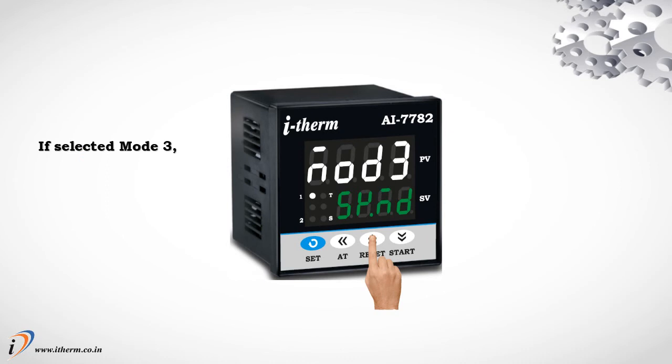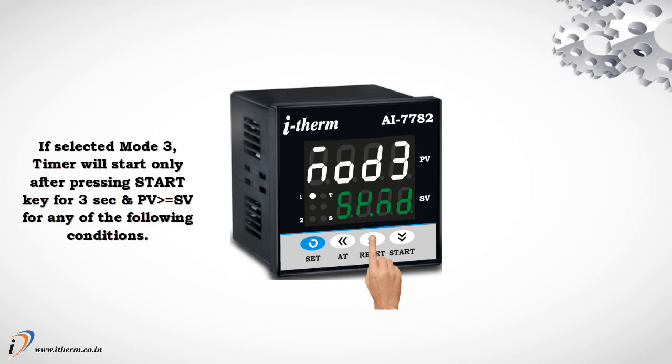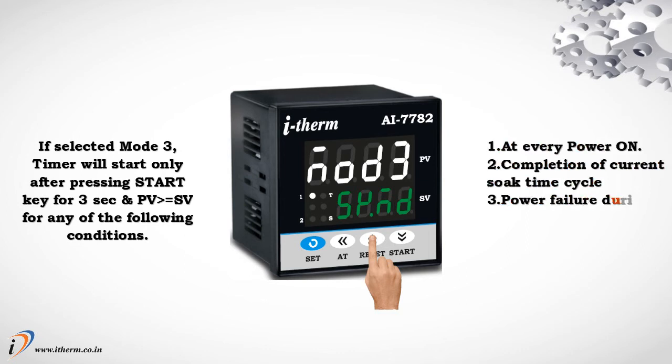If selected mode 3, timer will start only after pressing start key for 3 seconds and process value is greater than or equal to set point value for any of the following conditions. 1. At every power on. 2. Completion of current soak time cycle. 3. Power failure during soak time is in progress.